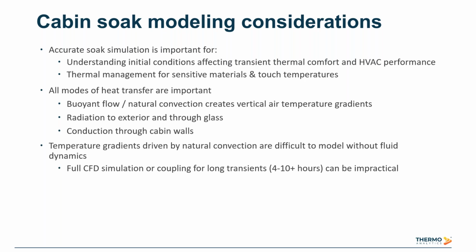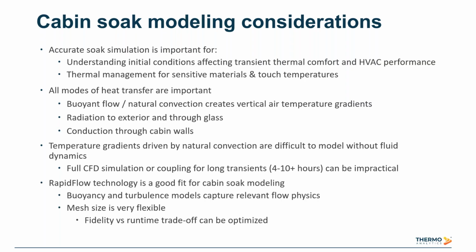Those temperature gradients within soaks driven by natural convection can be pretty difficult to model without some sort of 3D fluid dynamics. But it's often somewhat impractical to do a full conventional CFD simulation for the very long transients, 4 to 10 hours or beyond that we might have within a soak. So putting all that together, RapidFlow is a good fit for doing some of the cabin soak modeling. We can bring in a 3D fluid model and use a fairly coarse discretization so things still run reasonably fast. And we can use the buoyancy and turbulence models mentioned earlier to capture the physics we care about and sort of tune, again, the fidelity or runtime that we want out of a soak.